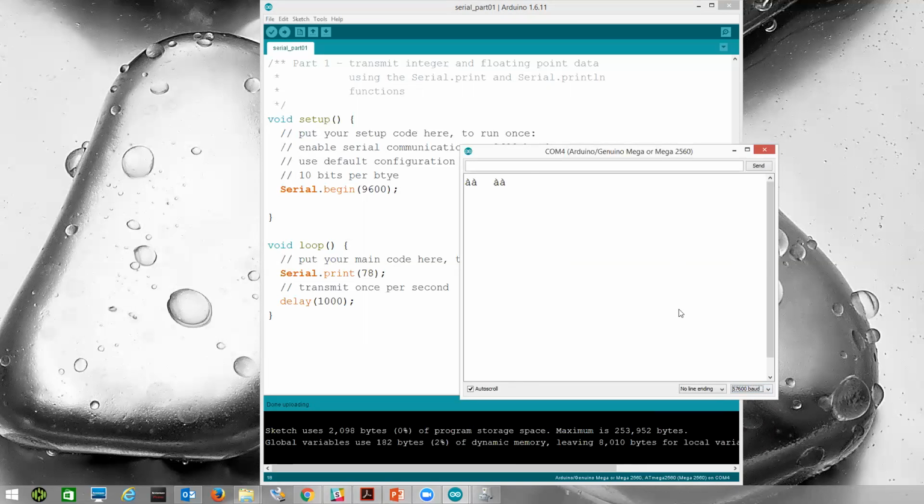So if you start getting what appear to be garbage values, you want to always check to make sure that your transmission software and your receiving software are both operating at the same baud rate. And notice there are fixed baud rate amounts. It's due to the clocks and all inherent in the hardware, so you can only use one of these valid amounts. You just can't use any amount. All right.